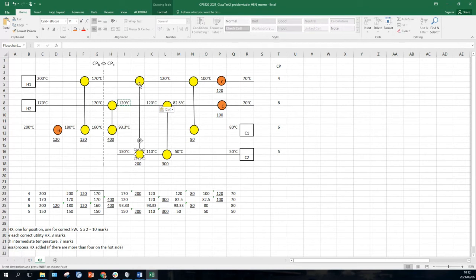So yeah, once you've got both, you can go on to your next match, and then you see that this temperature had to be a little bit higher so that you could actually make that match and reduce that from 480 to 400. This one we had to reduce from 500 down to 200, so we could get the right temperatures across there.